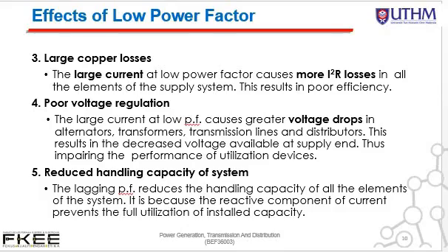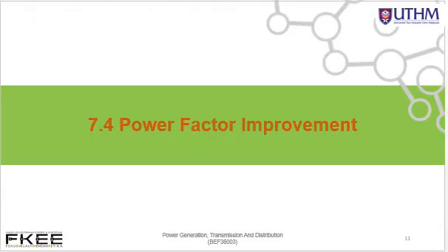The handling capacity of all elements within the system will automatically reduce and work below installed capacity. Considering the drawbacks of poor power factor, and to ensure that the system fully utilizes the installed capacity, power factor improvement shall be introduced in the network itself.